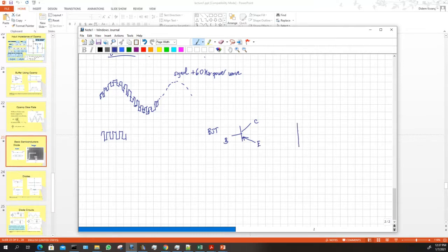And you'll also have this arrow going in the opposite direction. The arrow actually points from the P to the N. So this is actually a PNP. The N is the base, and the C and the E are P's, and I know because the P is pointing to the N. And then you can also have it this way. So this is still the emitter, this is still the collector, and this one's still the base. This is an NPN transistor. So these are BJT transistors.